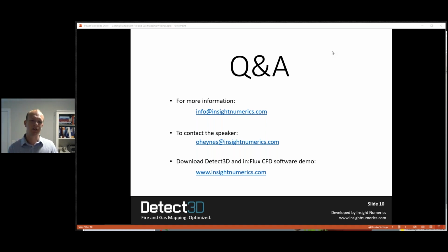For gas detection, often you don't run into that problem because the method for calculating the effectiveness of the gas detectors is much more simple. It's just using the spherical gas cloud. So the main issue with geographic gas mapping is deciding on a gas cloud size. That's normally something in the performance standard. It can be supported with CFD modeling of gas leaks if you wanted to get the gas cloud size, but that's normally the issue. Normally, there's no need for optimization of gas detectors using the geographic method.